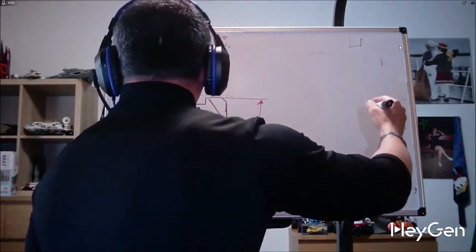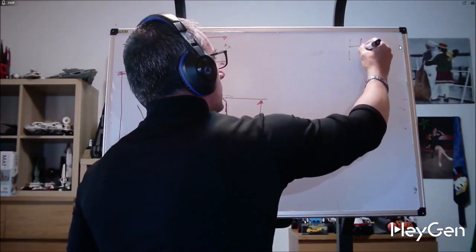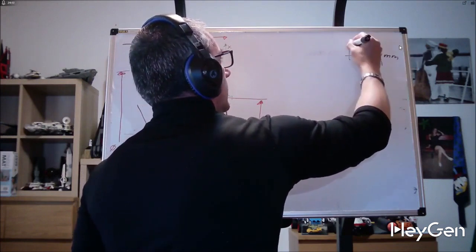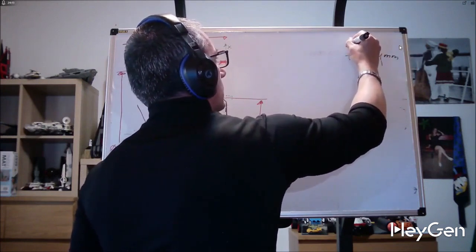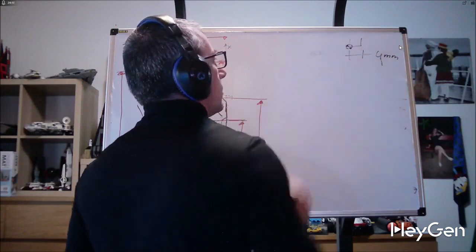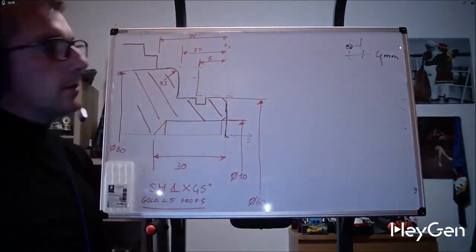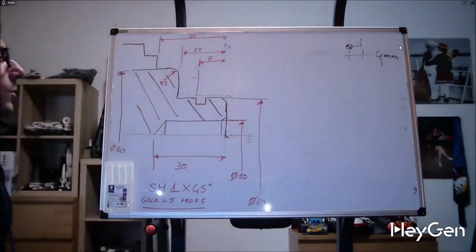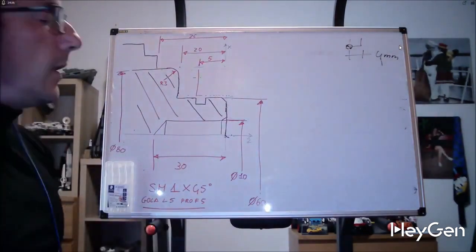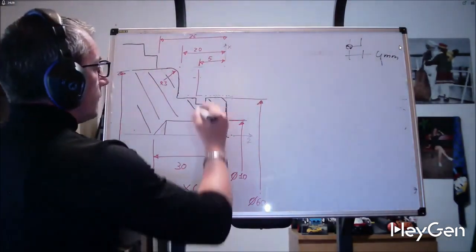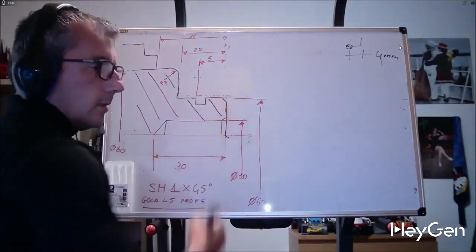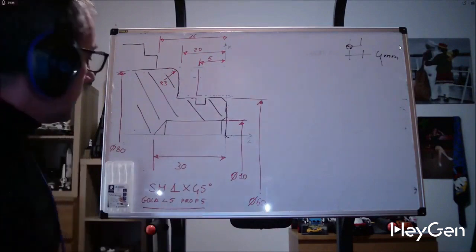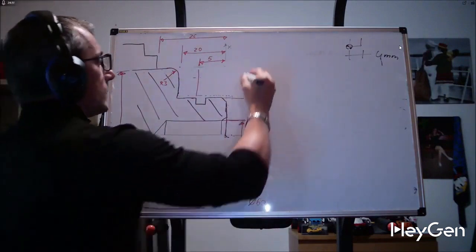Let's take our groove tool. We know that our tool has a thickness of 4 and we zero it. Well, we only need to move our virtual point according to X and Z, so our tool point. So what do we do? We should position ourselves in the middle of the groove, rough it, and then finish it.